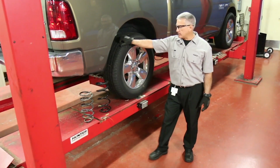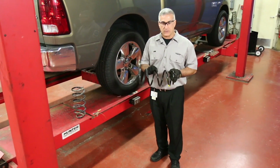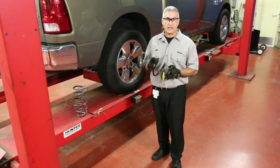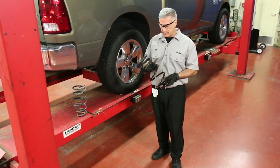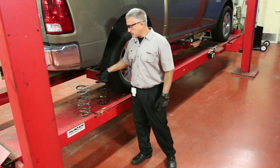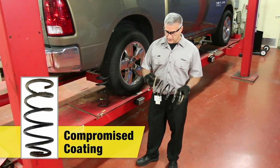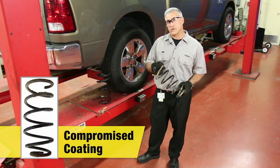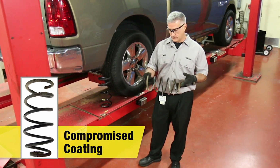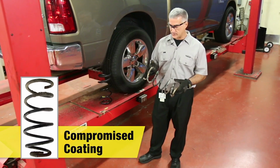Okay, so now let's talk about inspection of coil springs. Most modern springs are a very light diameter for improved ride and performance, but they have a durable coating, usually epoxy, to protect them and maintain that diameter throughout their life. As the spring gets older, the coating can get compromised, and the compromised coating will allow the coil to actually rust, which decreases its diameter and makes it weaker. So that's a good indication that the spring will need to be replaced because it will most likely fail once the coating is compromised.